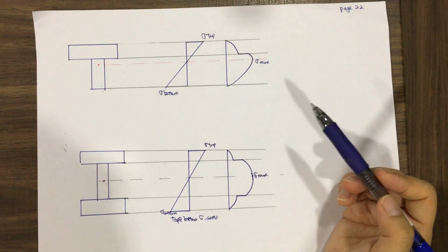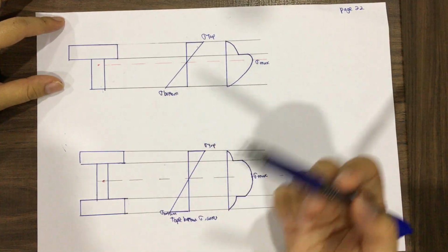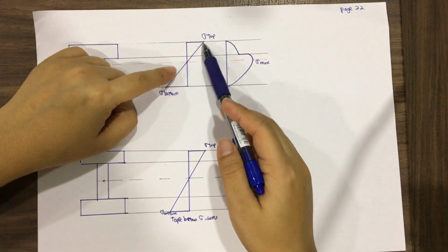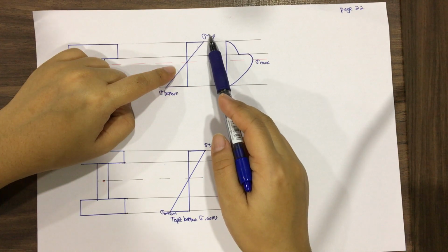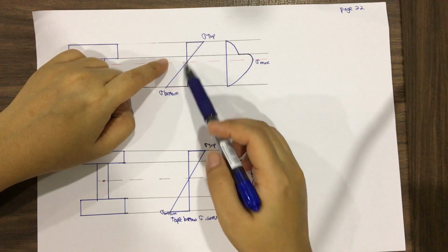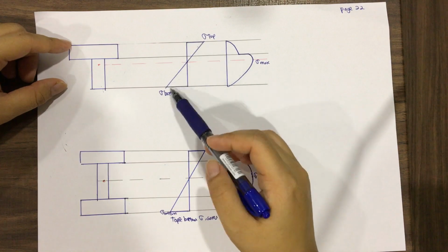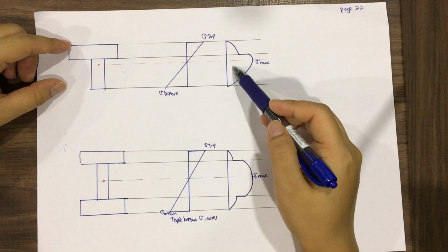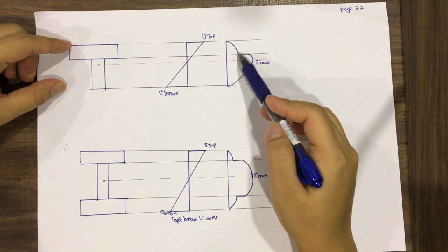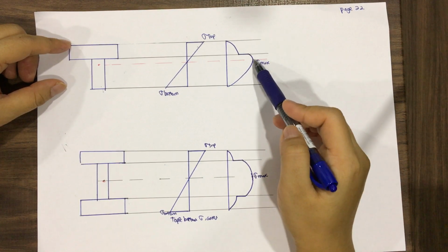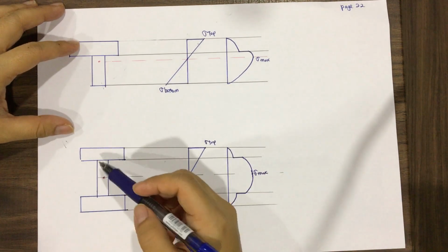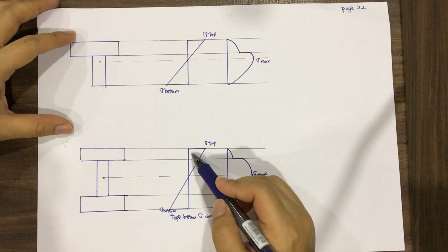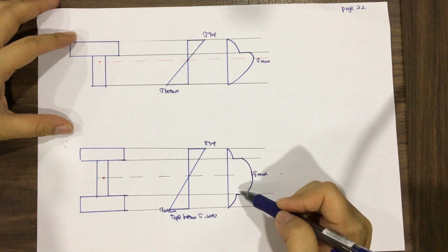So here I want to make a summary. For the T-beam, you will get this shape. This is the bending stress at top and bottom, which is uneven, not symmetric, because you will experience different values. And then this is the shear stress distribution. For the flange and for the web, these are the values, and this is the maximum. And here is the I-beam that I just explained. This is the symmetric normal stress, and also this is the shearing stress for that.